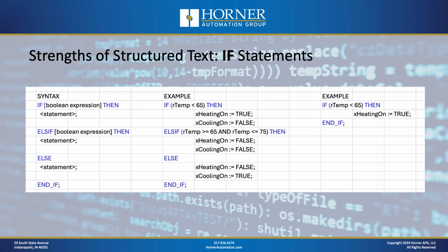I would advise people, some people coming out of college like to do everything in structured text. So you can do a little bit too much structured text, and ladder is good for Boolean logic. I would not do too much Boolean logic with if statements because people end up nesting them a little too deep. But if you keep your if statements simple, life is good. I agree. Yeah, no question. If statements are great, just don't go crazy with the nesting.